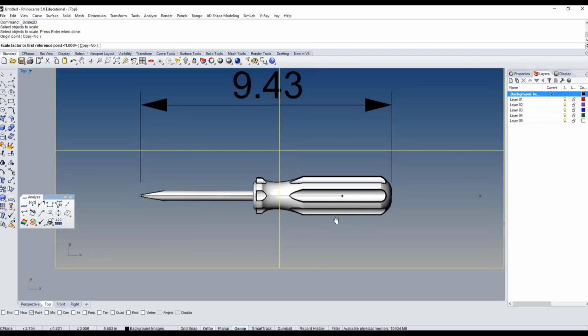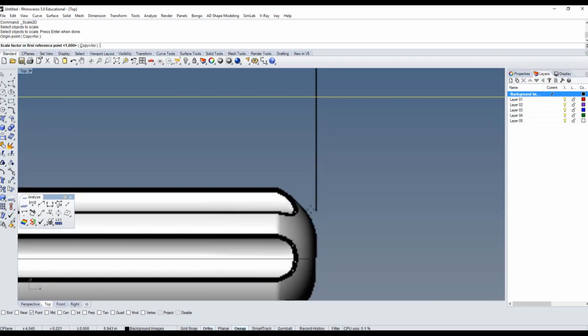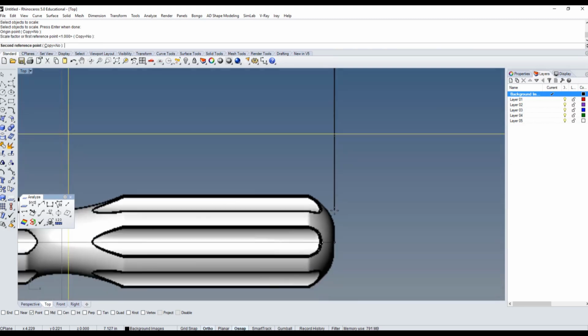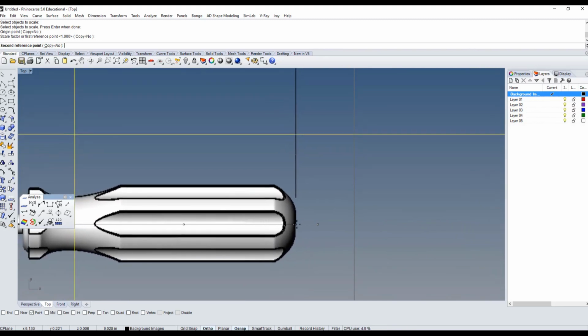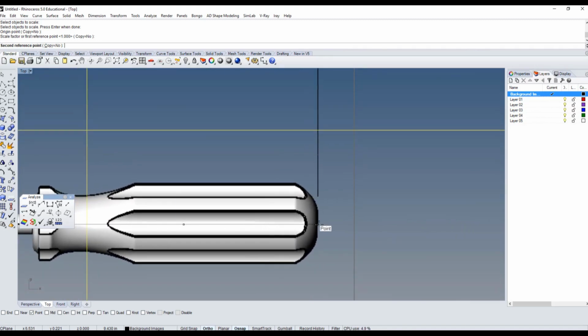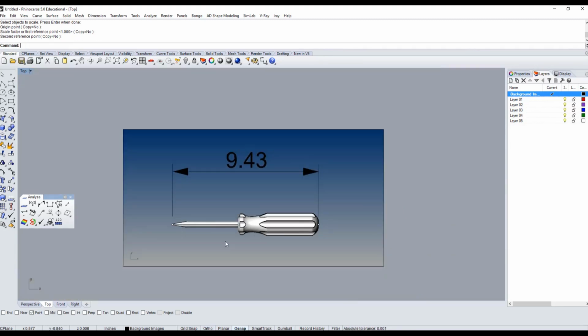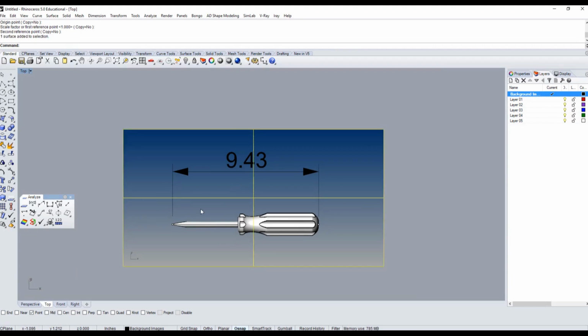I'm going to press shift, and I'm going to bring my cursor so that it aligns with this second line here. Okay, or you can actually click on the tip, it's up to you. So I'm just going to try and match to this line like this. And now I still maintain the pressure on the shift key, and I just bring my cursor on the point and I left click. So now I managed to match my drawing with the real scale in my 3D environment.